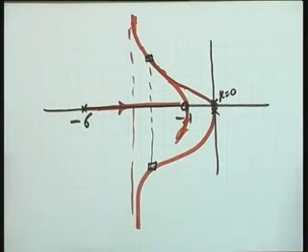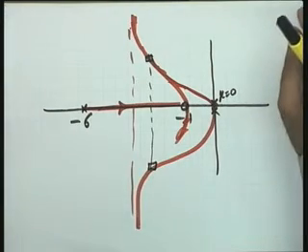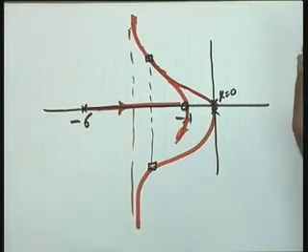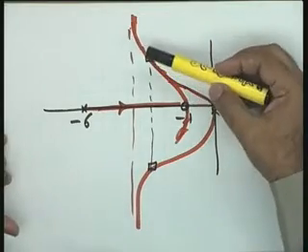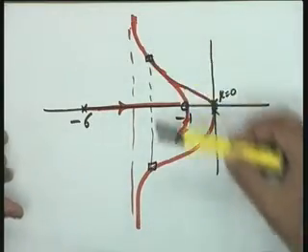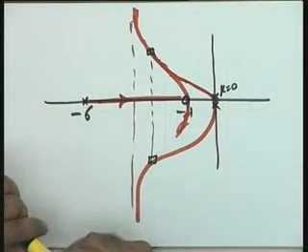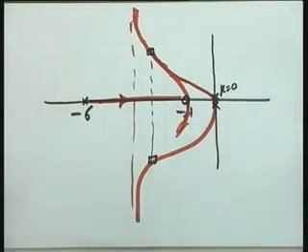So it appears in this particular case as if your design requirements have been satisfied, because your root locus branches pass through these 2 points which correspond to the transient performance. But for one point: how about the dominance condition?